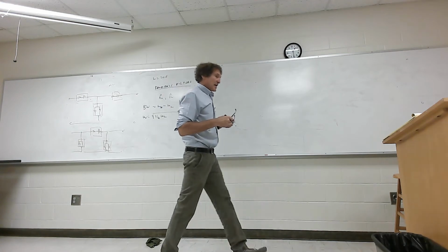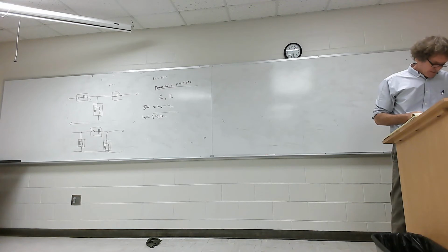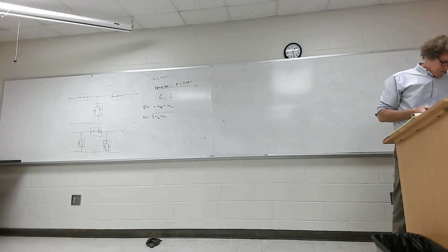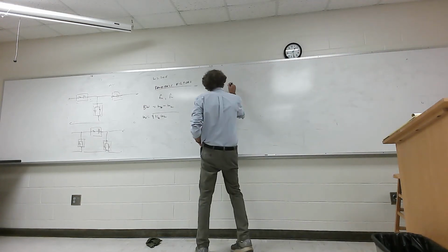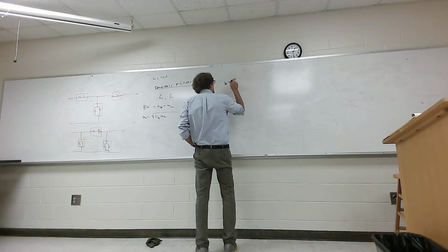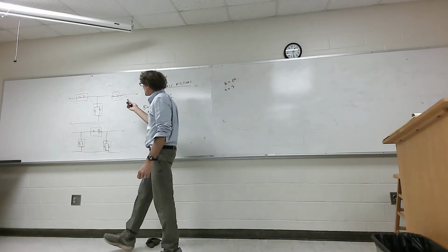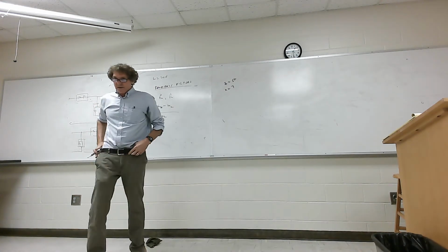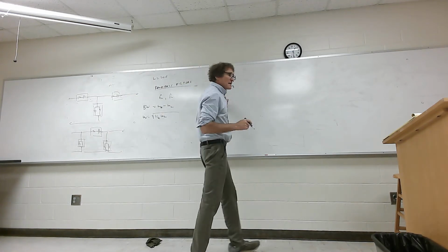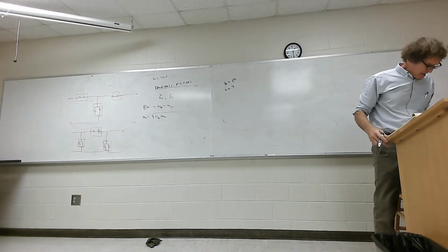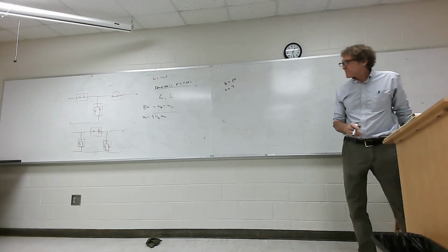After that, when we have those values, let's just do this one. This is example 10.17. He wants a third order Chebyshev bandpass filter for a 50 ohm system. So we have Z naught equals 50 ohms, and he wants the number of elements to be 3. When it says 3 elements, it means 3 blocks of elements, not 3 singular values, right? And there's 1 dB of ripple.